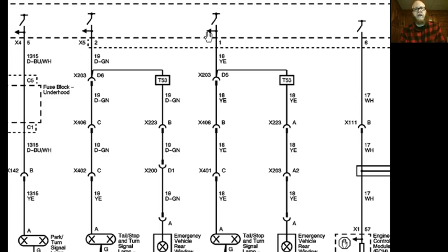And then these little arrows there are showing that there is a meter inside this module paying attention to whether or not there's voltage here. When this tail light is turned off, it's not going to have any voltage because it's not connected to power. When it's turned on, we'll see voltage there because we're on the power side of it. It hasn't dropped any of that voltage yet. This allows this module to create codes.